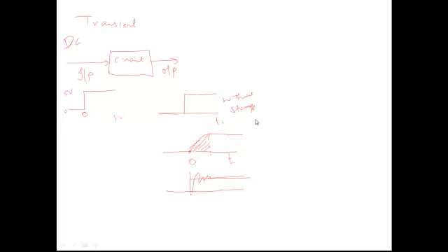But because of the presence of storage elements like inductance and capacitance, the output changes for some particular time, and only then does it reach a constant value. Similarly here, the output changes and after a certain time it settles down to a constant. The shaded area in both these output responses is called the transient.